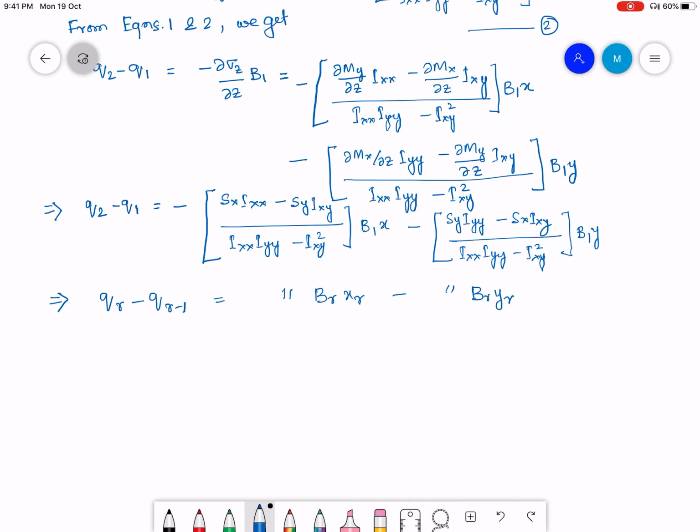Okay, so this equation is going to give me the expression for shear flow in a skin stringer idealized cross section. Now let us understand how much advantage, or how much easier calculation, this is going to give us.